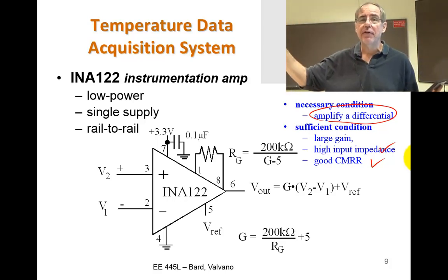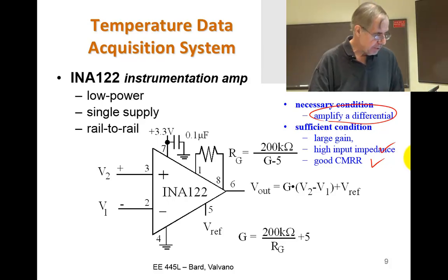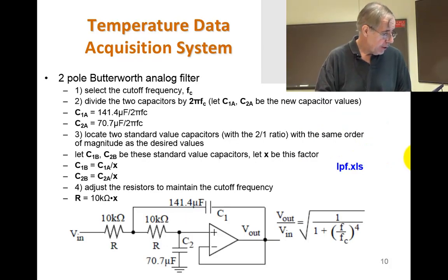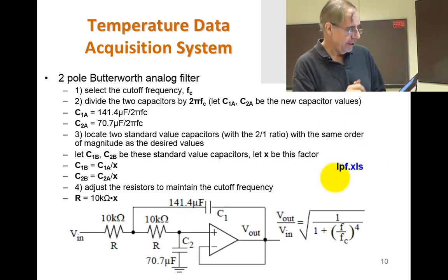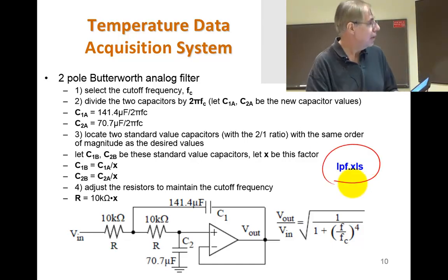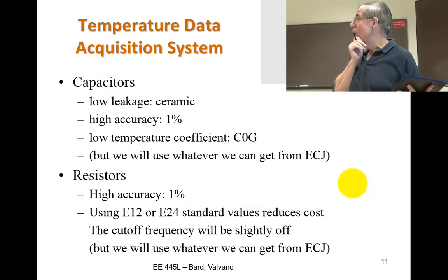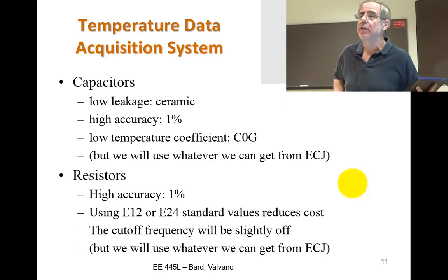All electromagnetic field pickups are going to come into the bridge and create common mode, which is why we use it. So we want to reject common mode. And I did that one. Again, when you're doing this, the math's not too hard. This is correct.